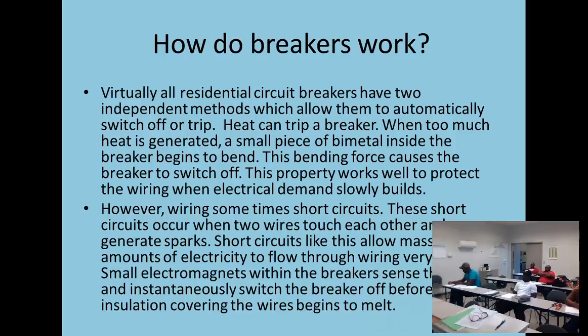Now, I will say this. As an HVAC contractor, if you're working for one or if you're one, you're not a licensed electrician, and the codes allow us to work to the disconnect. So if you have a disconnect outside, you're not supposed to go any further than that. However, if you're working on the inside where the air handler is, and instead of having a disconnect, they wired it right into the breaker box, that is your disconnect, okay?